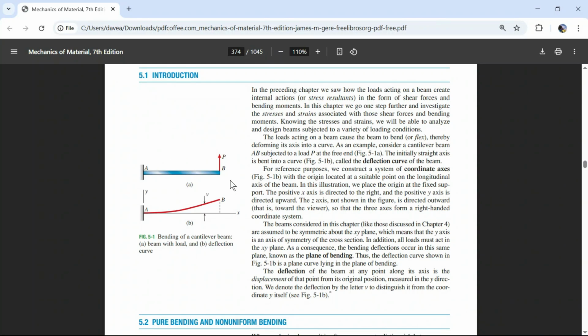If we have a cantilever, we can pull up on it. The take-home point is that if this was a slinky, each disc of the slinky would move up. That's shear. But we don't get a lot of deflection. This visible height right here is the small v, for the deflection in the y direction, and due to the shear forces, that's just not very much. But bending is a lot.